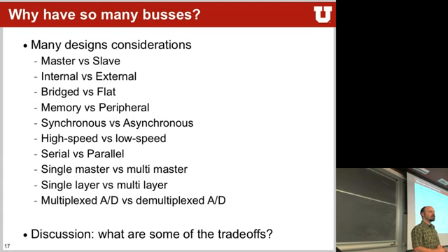Yeah. So if you have two systems that are apart from each other, they don't need to share a clock. You don't need to have a clock line going actually to the other guy. It's asynchronous. At the same time, synchronous buses are usually faster than asynchronous buses because you have the clock line. It's a lot easier to deal with synchronous buses than with asynchronous buses because you have a clock that can drive your digital system directly.